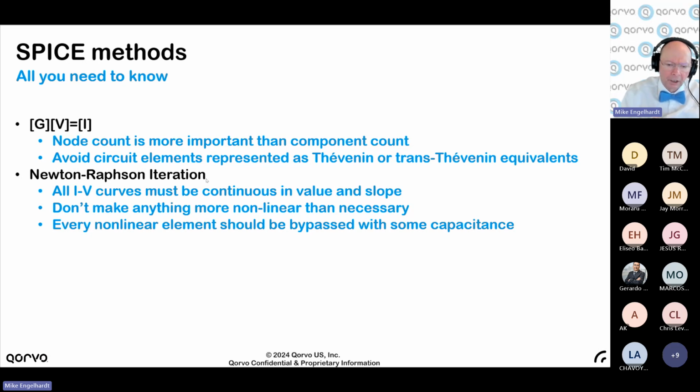If after a few Newton iterations you don't get the answer, you realize, this just didn't work. I've taken too big of a time step. I'm going to go at x plus delta over 2. And I'll re-expand my circuit in Taylor series about the time at x plus delta over 2, again using the solution at x as my initial iteration point for my Newton iteration, and try that. If that doesn't work, do delta over 4, delta over 8, 16, 32.